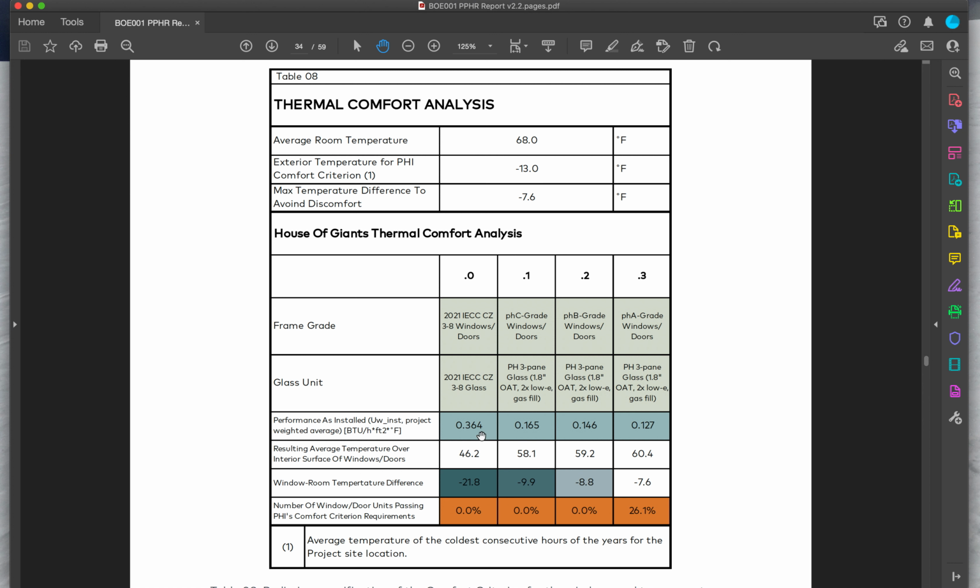Now, following the science and doing the math, the science of thermal comfort says that in order to feel comfort, or in other words, to not feel discomfort, the human body wants to have all the surfaces surrounding our body being the same. The same, so to speak, means that the maximum delta in temperature on the surfaces that the body allows before feeling uncomfortable is 7.6 degrees.